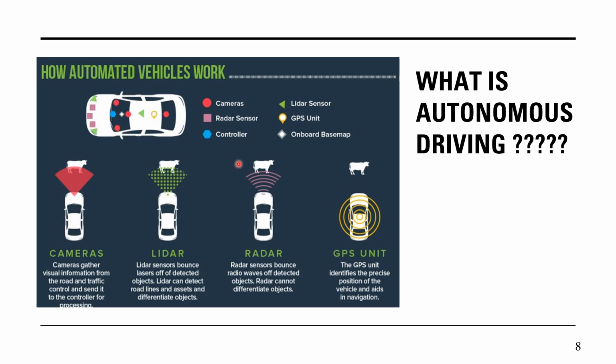Coming to radar, if you see here, radar has been established as a sensor, three sensors to detect objects coming in the long range, and these are mostly used in the adaptive cruise control feature to detect different kinds of cars or objects in front of the car and adapt the speed according to the target vehicle relative to the ego vehicle. And coming to the GPS unit, we have an established GPS unit in the vehicle for live monitoring or speed monitoring in terms of local navigation maps and so on.